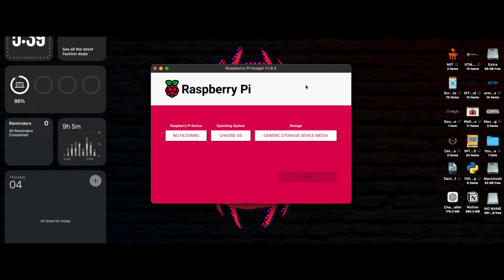And then what you are going to do is tell your Raspberry Pi to boot from a USB, right? So first, without turning on the Raspberry Pi, or without connecting it to your desktop, or without even doing SSH into your Raspberry Pi, you just have to configure the Raspberry Pi settings such that the boot order will go to USB first, and then SD card or NVMe or any other boot options you have, right? What we are going to do is open the imager, insert your secondary SD card,